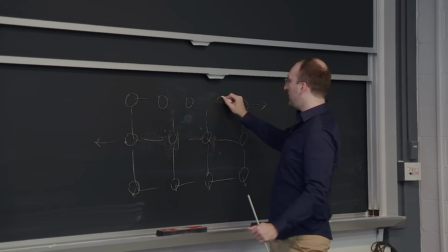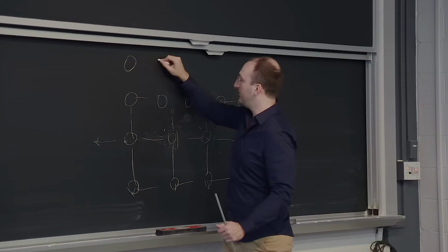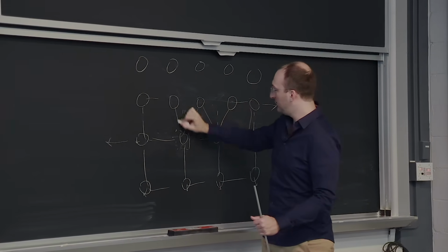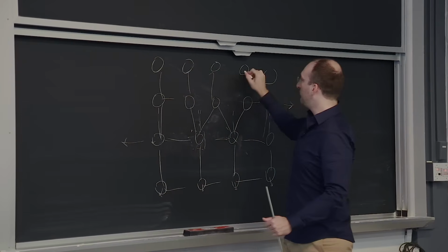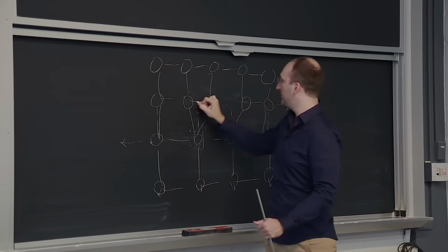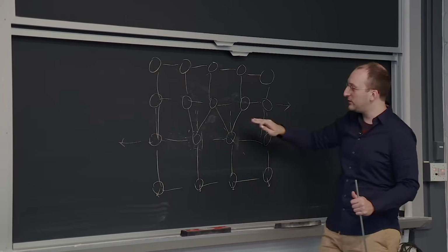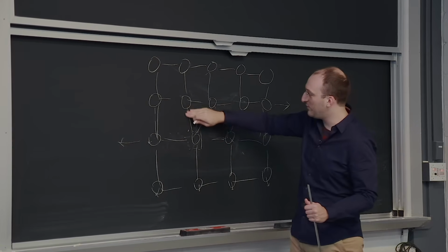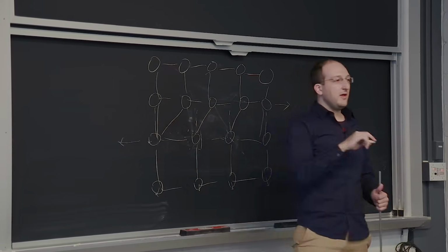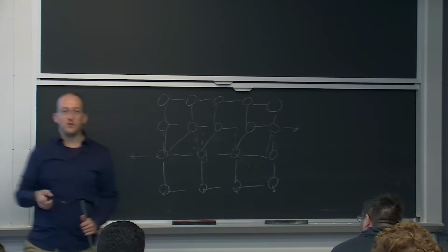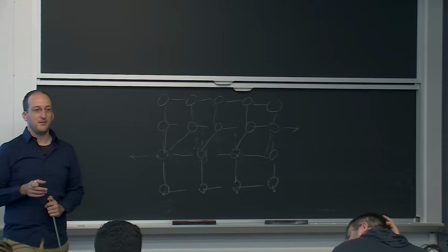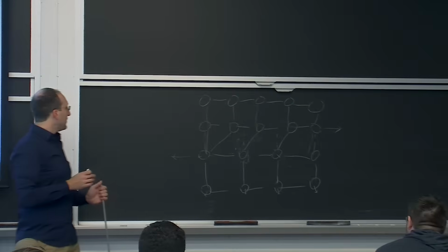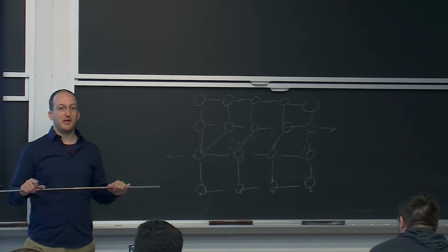if you shove an extra half plane of atoms in there, and the bonds are kind of funny like so, right at that extra half plane location, then what you can actually do is break one. Let's say you break this one, form the next one, then break this one, and form the next one. For a few atoms to move over, you only have to break a line of bonds, not a plane. So it's much less energy intensive to get a dislocation to move than to just break something in half.